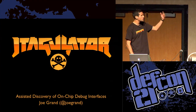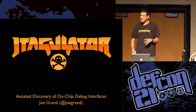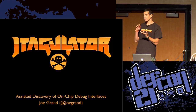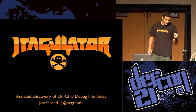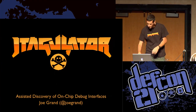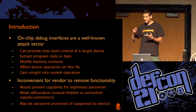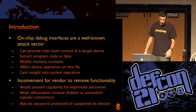Okay, so we're going to talk about JTAGulator. JTAGulator is a device I just put together, a fully open source device that will let you hook up to 24 unknown test points on a circuit board, and it will detect if there's any sort of JTAG interface, which is an on-chip debug interface, or also UART interfaces, so things like root shells, serial debug ports, whatever. I'm going to go through an introduction about the design, the process, how JTAG works, how UART works, and then, of course, give you demos of all of this stuff.